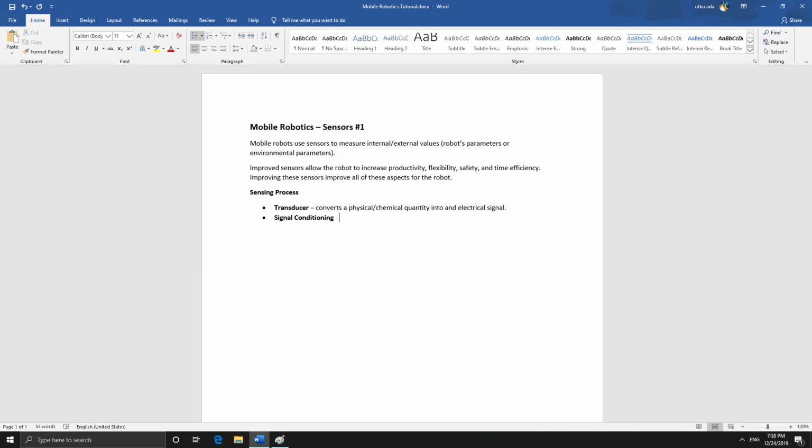this is used to ensure a linear relationship for the measurements of the sensor. So we want whatever the measurement is to go up linearly or down linearly, which actually makes it possible to gauge the output signal. If the measurement changed erratically for an increase or a decrease, then it may be impossible to actually make use of the measured value.